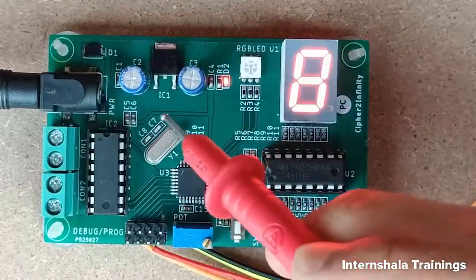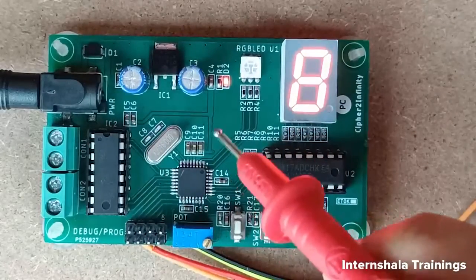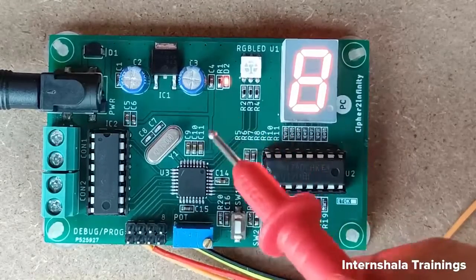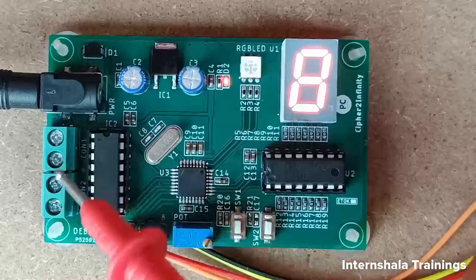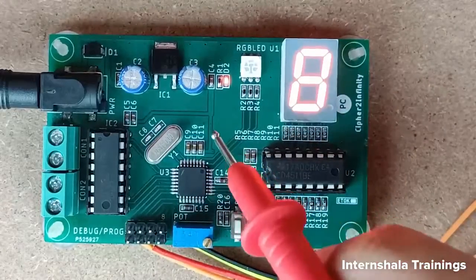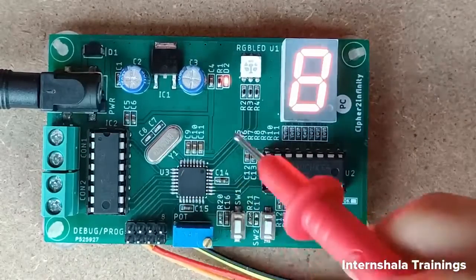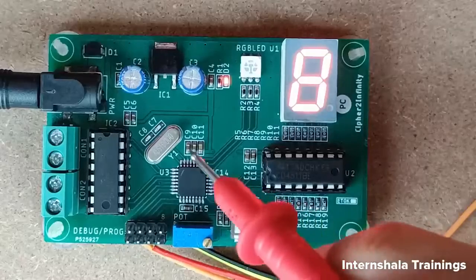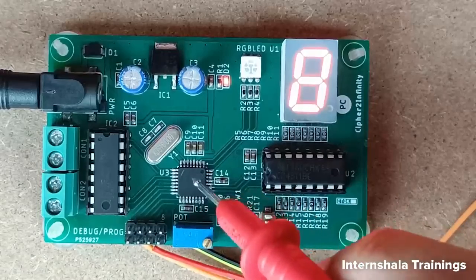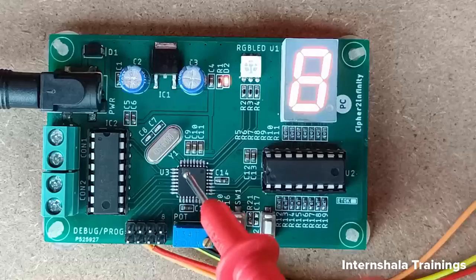Alright, so in the previous video, we saw that the power supply section is working perfectly fine, and it's producing 5 volt on the output side as expected. So it means that all the peripherals which are working on 5 volt on this particular PCB are getting 5 volt. Now, as we are testing the microcontroller section in this video, first of all, we will check whether all the VCC pins present on this microcontroller are getting 5 volt or not.